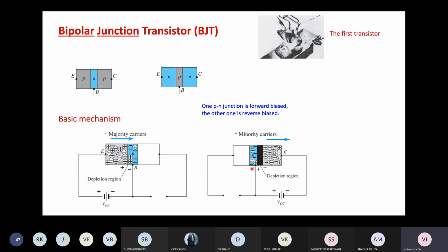Yeah. So generally, everything is about electron movement actually. If we are saying that the holes are moving, it means that electrons are moving in the opposite direction. And if we are saying electrons are moving, then electrons are moving in that direction. So generally, it is only the electrons that are moving through the wires. Because a hole is not an actual particle; it is a quasi particle, so to say. It is a mathematical model of a vacancy in the system. So ultimately, it is electrons that travel physically in the system.